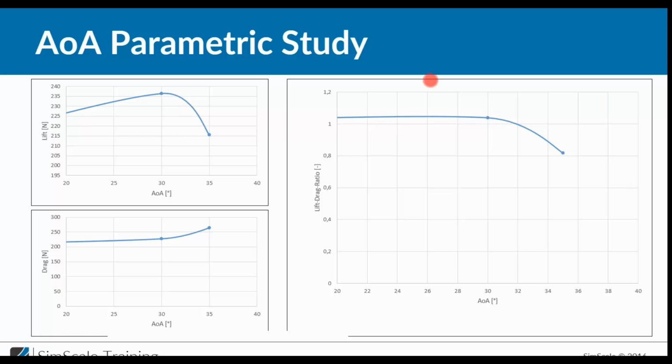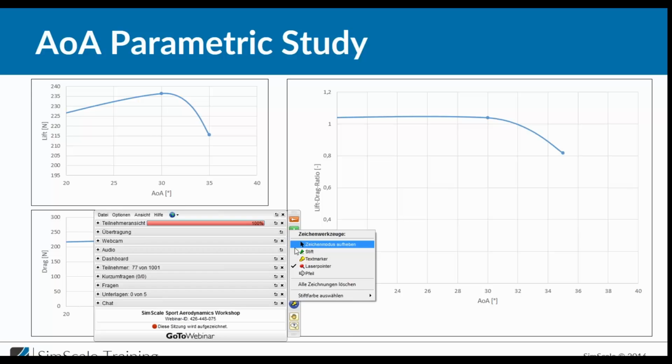So Akram, I would say as long as you're below 30 degrees, it's more like a control parameter you can use to decide in which phase of the flight you are. If you increase the angle, you will lose more speed, yet you will also decrease your sink rate. But if you go above 30 degrees, your lift will massively drop. So the first lesson here, in a nutshell, is that there is a critical angle of attack, and once this critical angle is reached, it's not a good idea to increase it anymore. Yeah, exactly. This is the point.